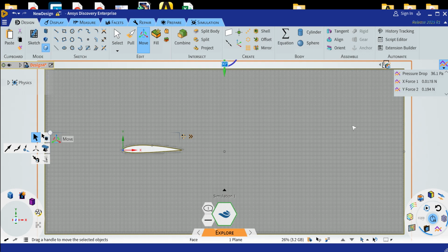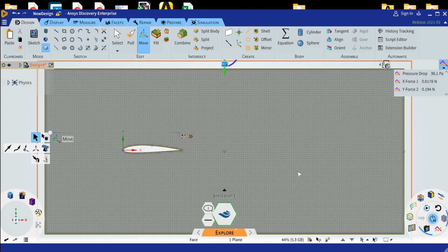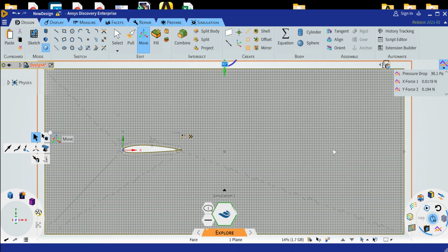How to control it? You see this explore fidelity. If it is pulled this way, that means a very fine mesh will be generated. You see the meshing is happening. The white color shadow is moving. You see it is very fine now. Or I can make it to this extreme so that it will be very coarse. Okay, better I will keep it coarse in other areas. Then I can refine only on this model.